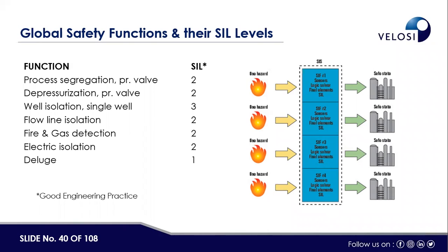Similarly, under the operational phase SIL assessment exercise, we have seen that when a client SIL team is sitting and making the analysis, they may say no fatality would occur, nobody would get injured, or there would be no damage to the plant of more than $1 million or $2 million, and so on. In that way, every SIF will come under SIL 0 or SIL 1, the lesser SIL classification zones. In that scenario, if the SIL is lesser, the interval would be longer.